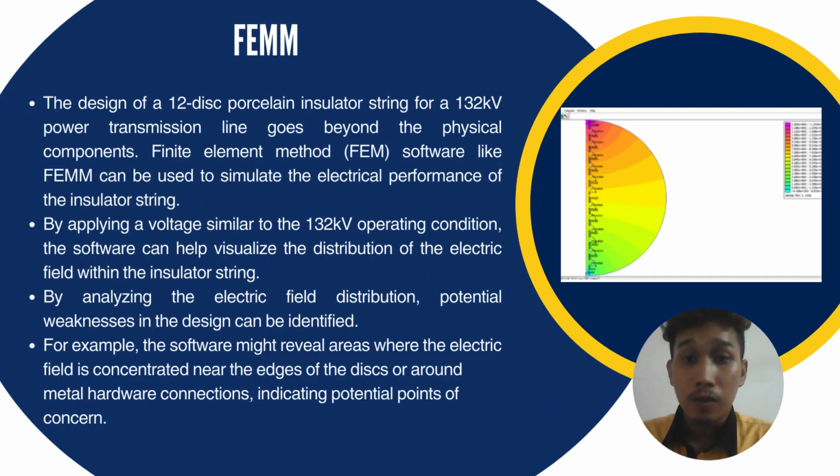Okay, we go to the FEMM software. The design of a 12-disc porcelain insulator string for a 132 kilovolt power transmission line goes beyond the physical components. Finite element method software like FEMM can be used to simulate the electrical performance of the insulator strings. By applying a voltage similar to the 132 kilovolt operating condition, the software can help visualize the distribution of the electric field within the insulator string.